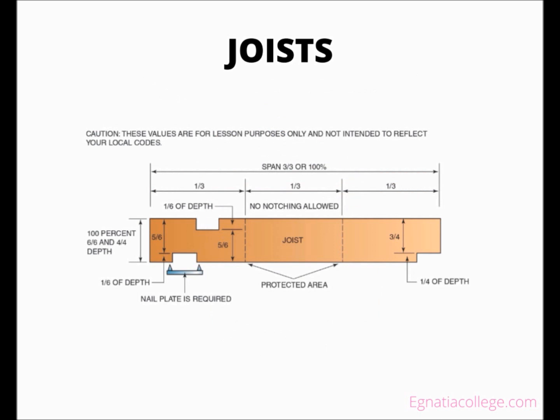A carpenter often notches the ends of a joist during the framing phase of construction. A plumber might also have to notch a joist to install piping that conflicts with the joist, but strict codes dictate the maximum depth of the notch. Some codes dictate that the end of a joist cannot be notched more than 25% of its depth.